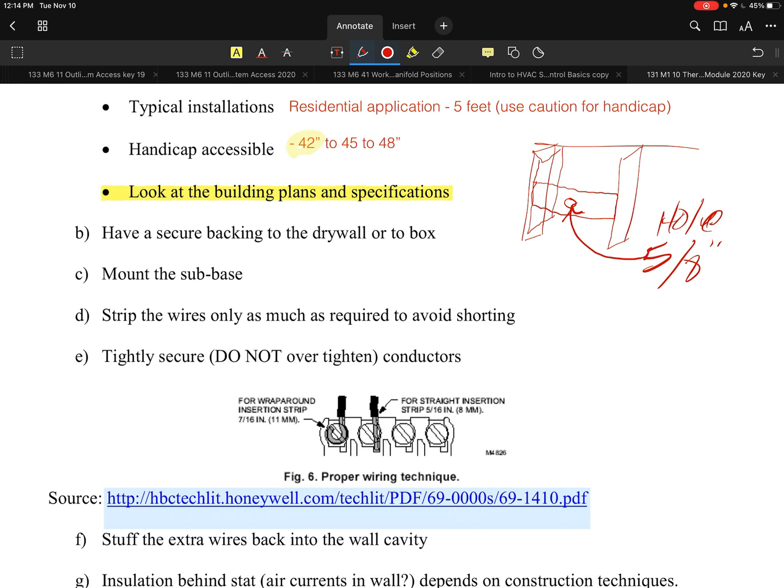So again, I would just look at that. Sometimes guys will take a 2x4 or a 2x2, but I think plywood seems to work the best. It's kind of light, yet it provides solid, strong backing. I've even done it where I took a piece of 1x4 pine and put it as the backing, and it works really good.